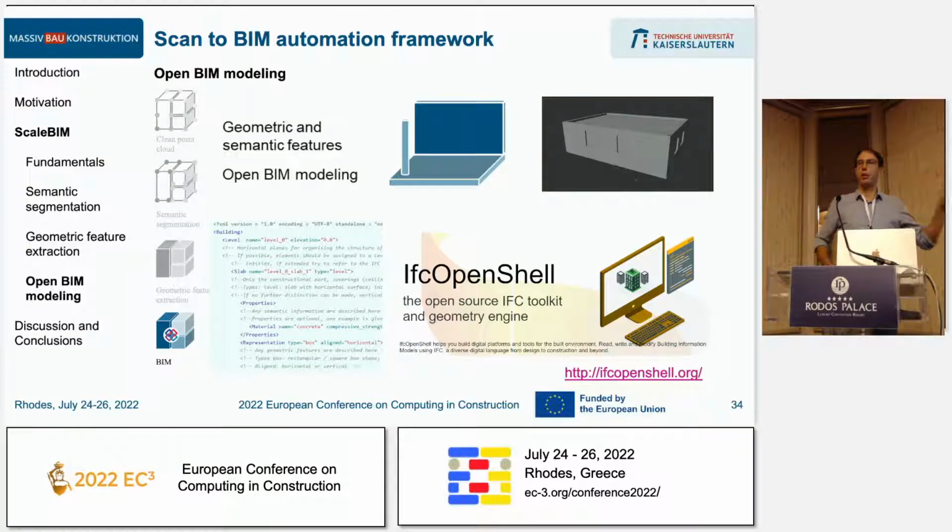So for now, we do an intermediate step here, taking all the information and putting it together into an XML-ish file. You can see it here on the bottom left. It is structured like the building would be. Essentially, for later work, you can use such an XML representation to also bring it to proprietary data formats.